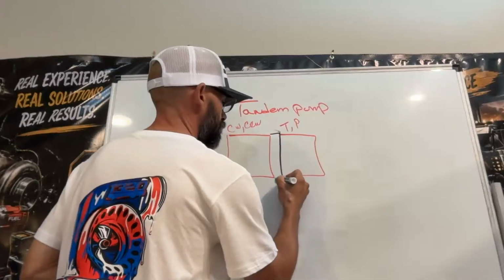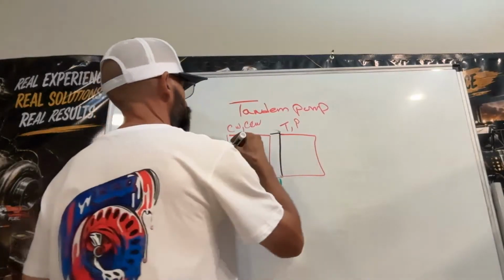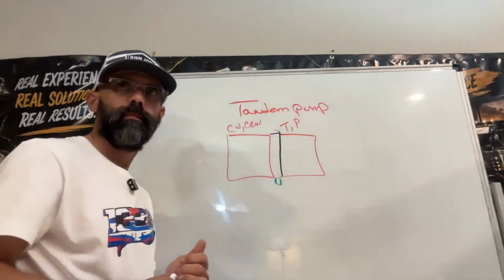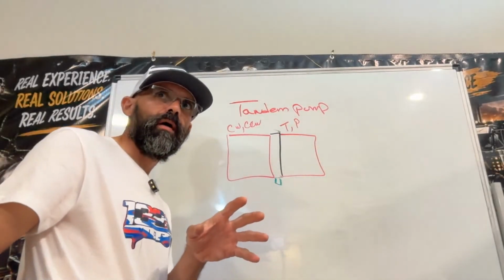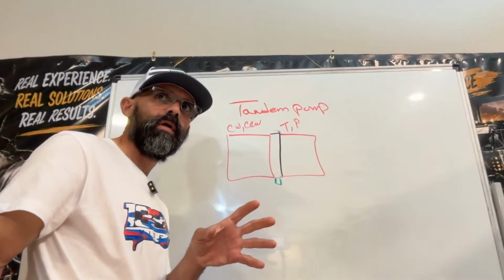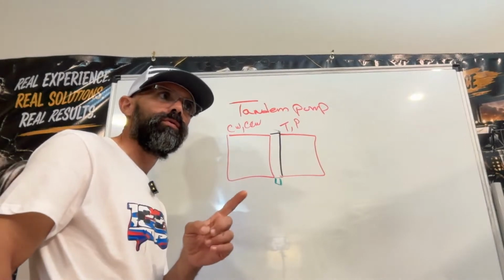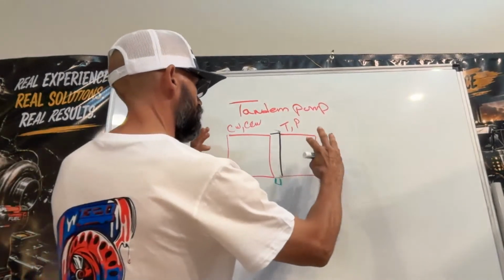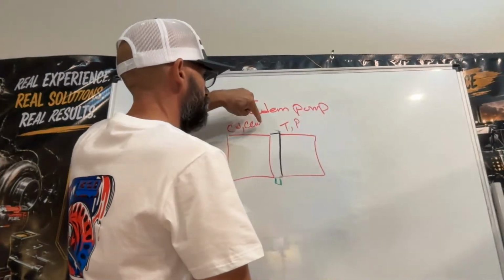Back here in the middle plate, on the middle section, you're gonna have your relief valve on those specific drills, except for 2022 Series 2 and 1620s. Because of the position of the pump, the relief valve ends up on the top.